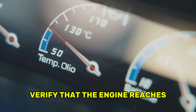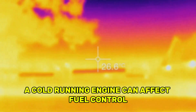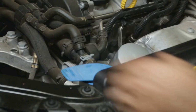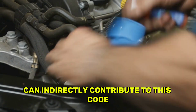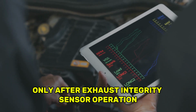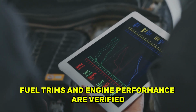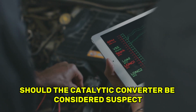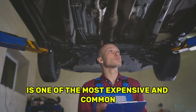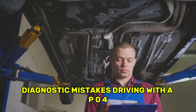Verify that the engine reaches proper operating temperature. A cold-running engine can affect fuel control and catalytic converter efficiency. Cooling system problems can indirectly contribute to this code. Only after exhaust integrity, sensor operation, fuel trims, and engine performance are verified should the catalytic converter be considered suspect. Replacing the converter without proper testing is one of the most expensive and common diagnostic mistakes.